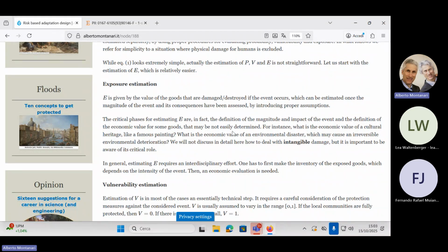overflowed and formed the flood water, for each value of the volume of the flood water, we estimate the area. We map the area reached by the water, and then the buildings, and then you have to also estimate the velocity, because what makes a flood impactful, more than the water depth, is the water velocity. So you may have even a limited depth, but with high velocity, it's a problem. So it's not only depth, it's more the velocity of the water.